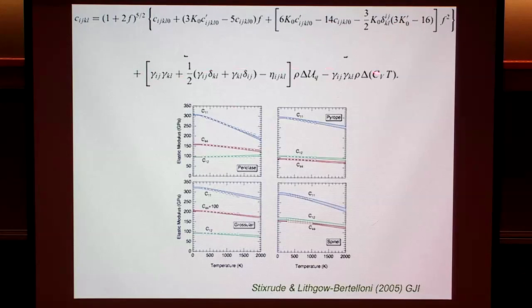And the temperature dependence ends up looking like this. This is the Gruneisen tensor. So I showed you before that for isotropic materials, gamma is V times dP/dU. For anisotropic materials, which is all crystals, it's dσij/dU. So it's a tensor actually, and this is the strain derivative of the Gruneisen tensor here.